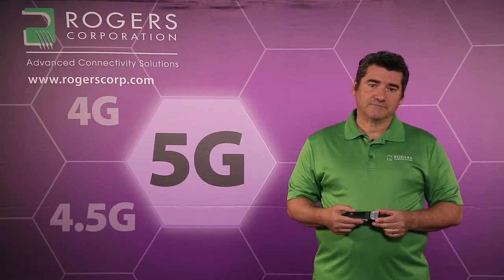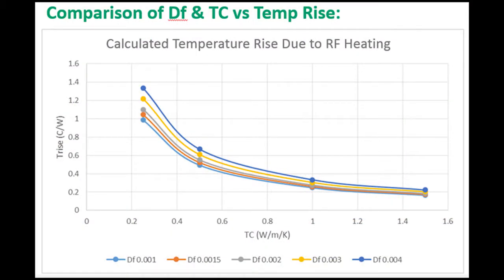and therefore temperature rise. In this graph, calculated, we have what temperature rise is for materials with various loss tangents, from a loss tangent of 0.001 all the way up to 0.004, while keeping all other parameters the same. You can see that when you have a very, very low loss tangent but a very low thermal conductivity, yes, indeed, at 0.2, there's more dispersion of the values based on the DF.